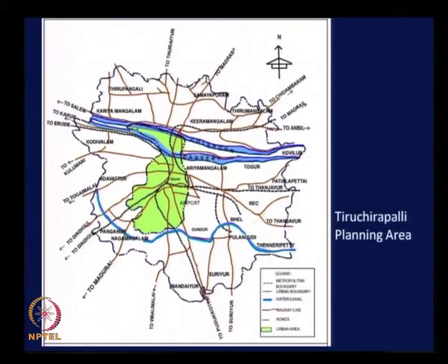So our distribution discussion is concerned with the 49 zones within the urban area. It is possible to mark off some areas and still analyze the distribution of trips. The only thing is, you must leave off the trips which go beyond your urban boundary. Consider all the trips which are getting distributed within the urban area and then do the trip distribution analysis. It is possible.